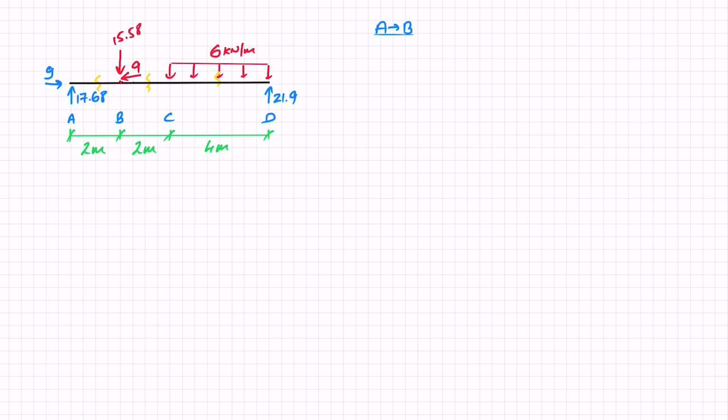Let's draw out our part of the beam. Here we've got this force of 17.68. We've got this reaction force of 9. We don't have anything else between A and B. X1 is going to start from here, and X1 is going to be between 0 and 2 when I'm going to start my next cut, when I have this new force that comes. And I've now exposed these internal forces, so let's draw them all out.